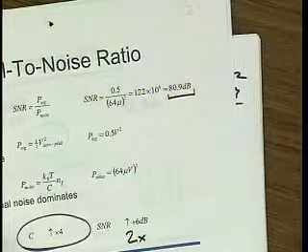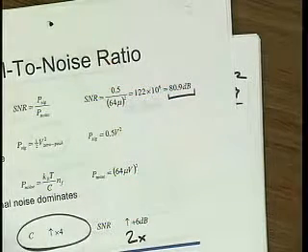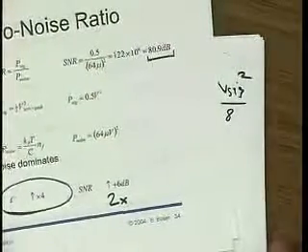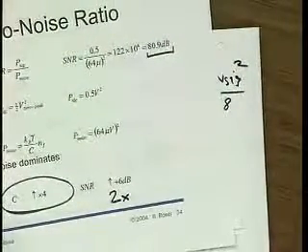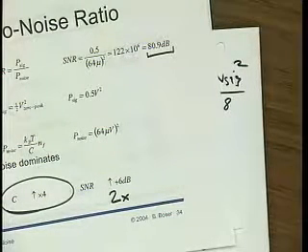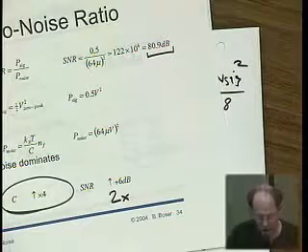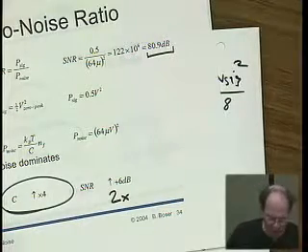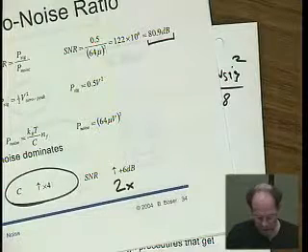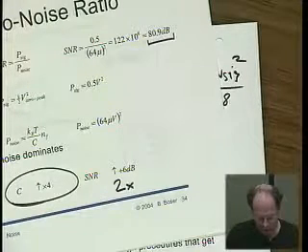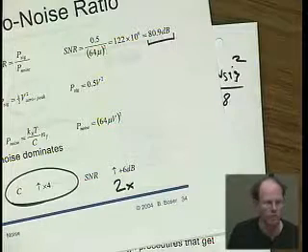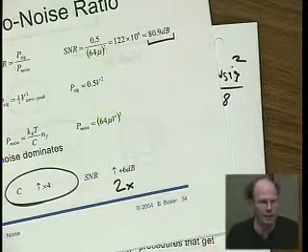Yes. So sometimes you're talking about a power signal to noise ratio, and sometimes a voltage signal to noise ratio. Do they specify that usually? No. The signal to noise ratio is always calculated as the ratio of power. It's the ratio of powers, but then when you go to the dB scale, we use 10 times log 10 of that ratio, right?